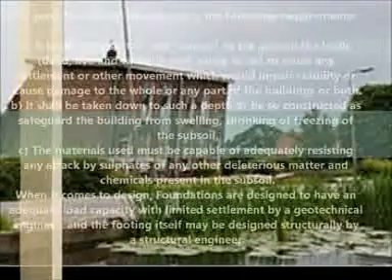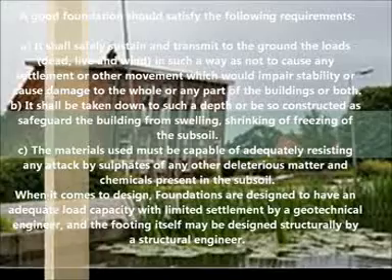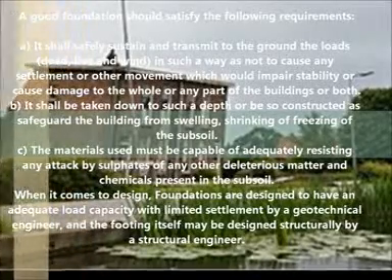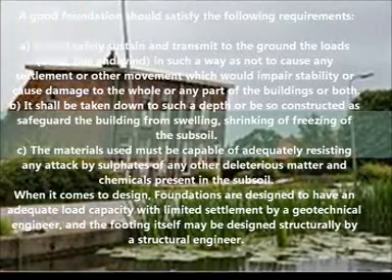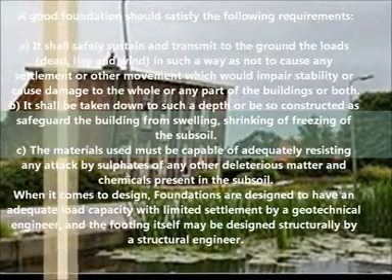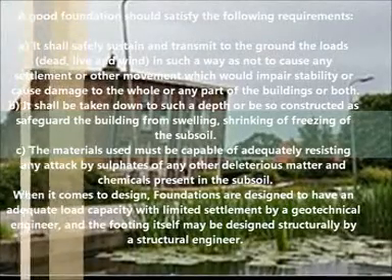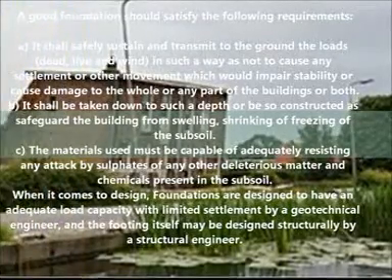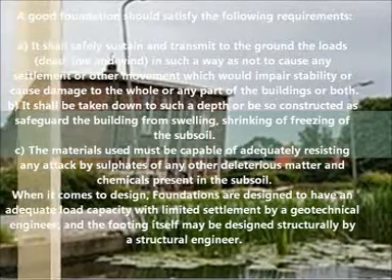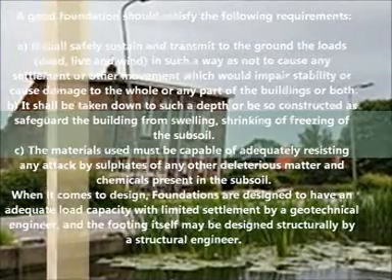A good foundation should satisfy the following requirements. A. It shall safely sustain and transmit to the ground the loads, dead, live and wind, in such a way as not to cause any settlement or other movement, which would impair stability or cause damage to the whole or any part of the building or both.